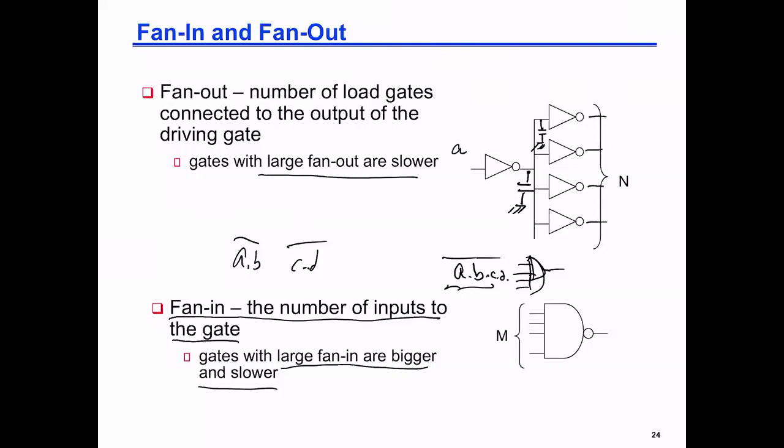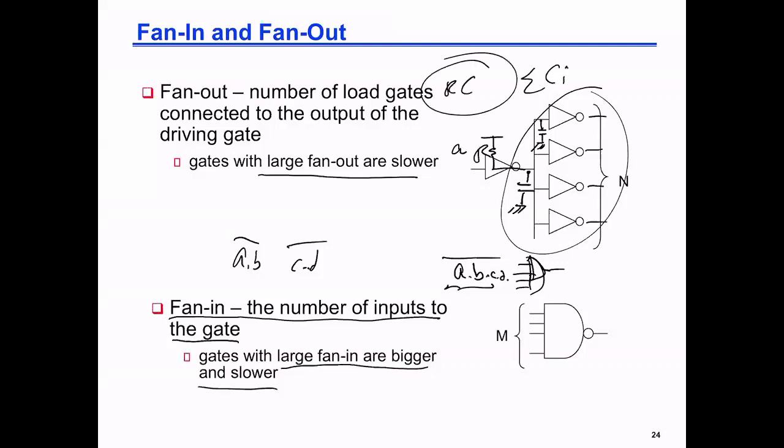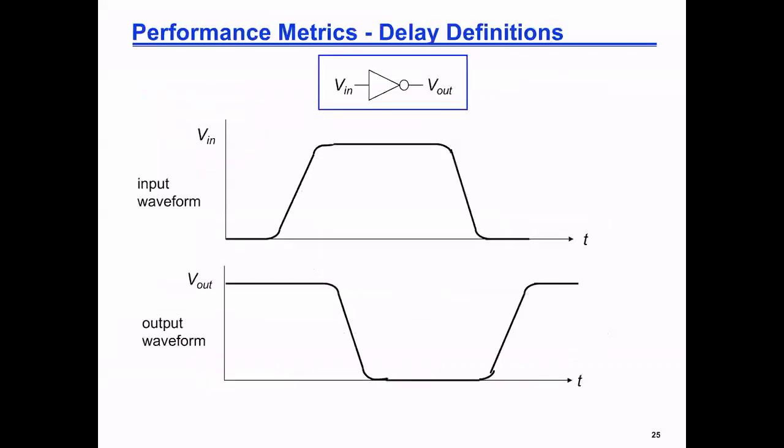And really, what is this? This is a current source, right, which has an effective resistance, and it is in the end some resistor, right? Yep. So the equivalent circuit, which we will study later, will be an RC circuit. If you load it with many capacitors, this will be large, and the RC time constant will be very large. Okay, thank you. So we will explain all of these concepts later, but I'm going to talk today about the delay and about the RC time constant.